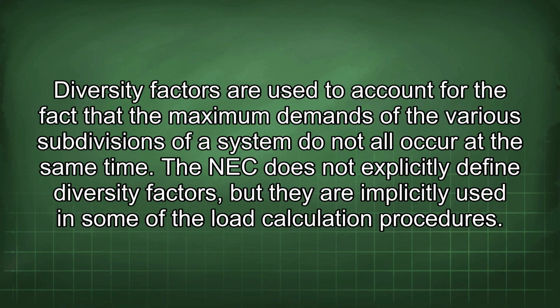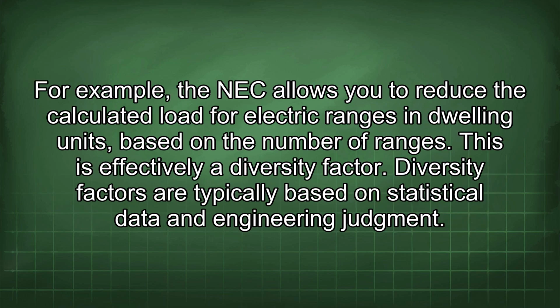Diversity factors are used to account for the fact that the maximum demands of the various subdivisions of a system do not all occur at the same time. The NEC does not explicitly define diversity factors, but they are implicitly used in some of the load calculation procedures. For example, the NEC allows you to reduce the calculated load for electric ranges in dwelling units based on the number of ranges. This is effectively a diversity factor.